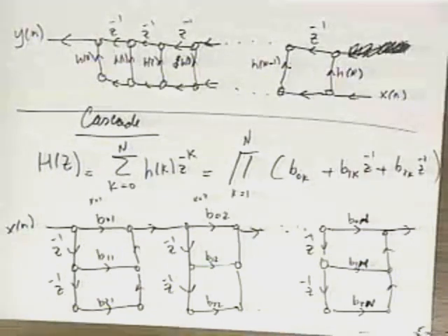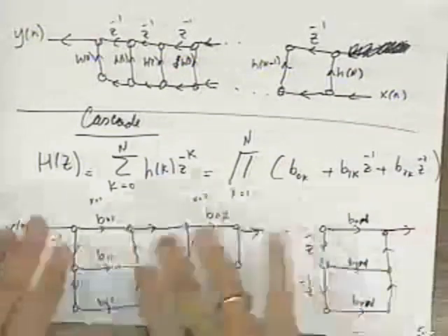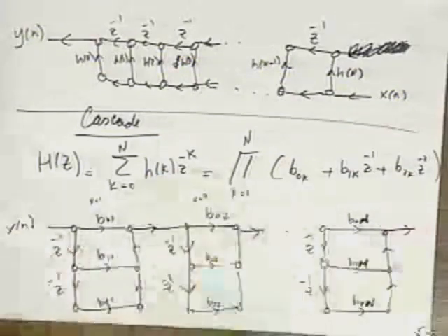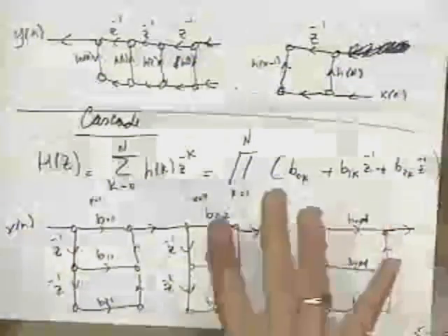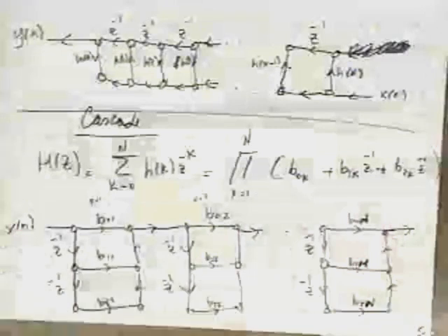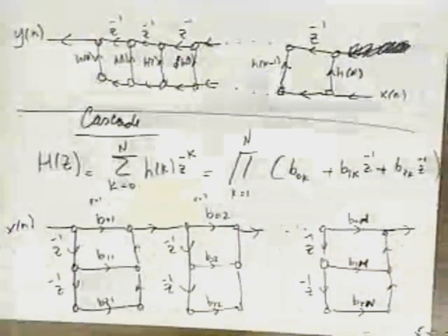The poles move the least. Whereas in direct form, if you have an nth order system and you build a gigantic direct form 1, the locations of the zeros move a lot more in that direct form 1, 2 type structure than they would in the cascade. So in some sense, the cascade structure is the structure of choice if you worry about finite word length effects. And again, we will talk about that after I talk about design of filters.